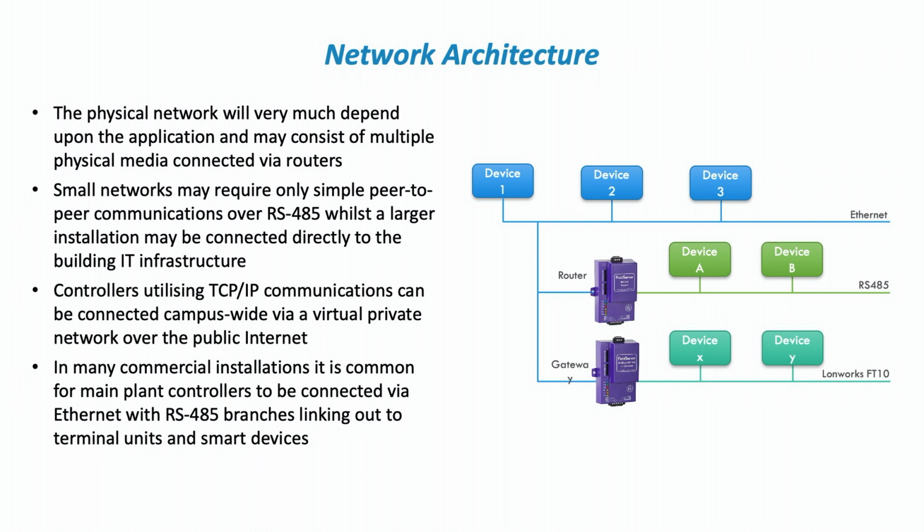In terms of network architecture, notwithstanding MQTT, a very common form of putting our networks together is we have high-level devices sitting on an Ethernet backbone. So if you think in terms of real controllers, if you've got a Trend system, for example, Trend IQ4 controllers are all equipped with Ethernet ports. So you would connect them together with Ethernet.